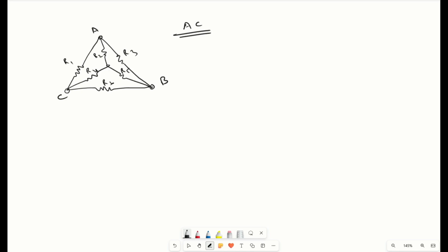As here also we can see there are no combinations like series or parallel, everything seems to be mixed up. So in this case also we have to convert from star to delta or delta to star. If you see here closely, the middle connection provides a star connection, right? So if we convert this into a delta, it will be like this, right? I am using a different color for understanding. So this star will convert into this form, in this format. If I check what I will be getting after conversion, it will be like this.